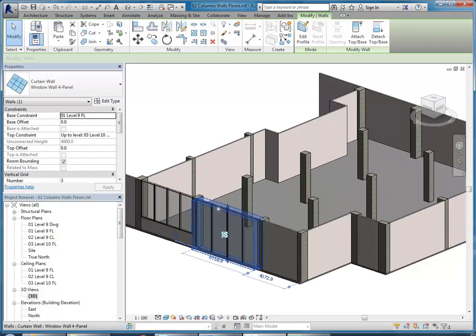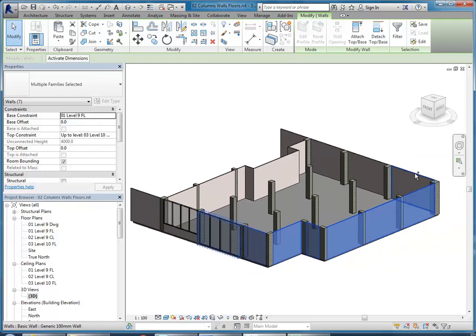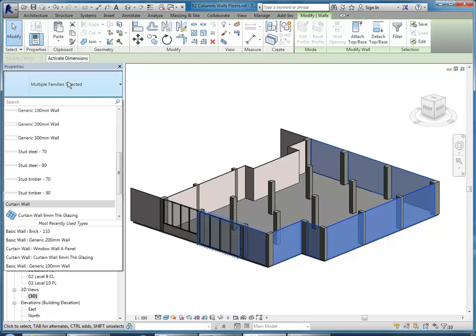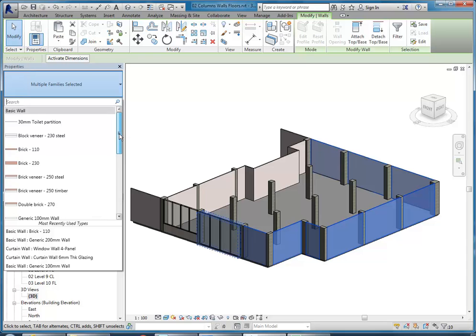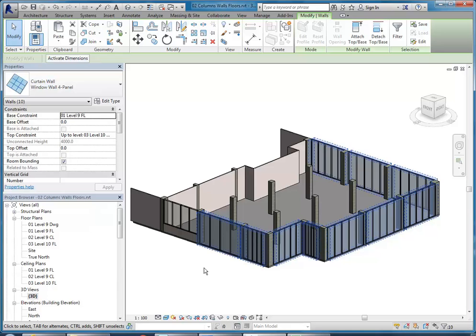if you want to put all of that in one go to replace these existing walls, you need to select them all with control, and then change the wall type to your curtain wall. Again, set the base offset to 1000. Thinking if this is the quickest way. Yeah, I think it is going to be the quickest way.